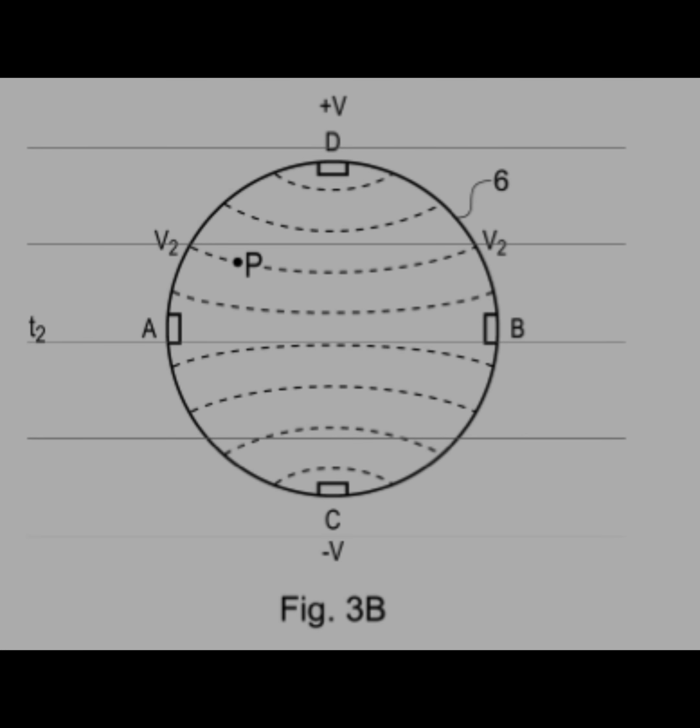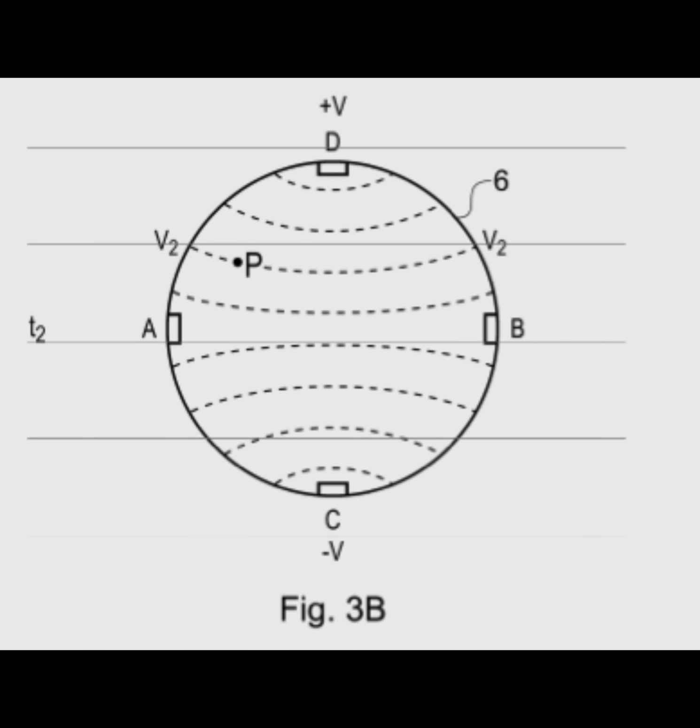Figure 5 shows a graphics tablet 21, which is a third embodiment of the invention. This graphics tablet comprises a panel and an actuator 24 which can be freely moved. The panel comprises a flat support 22 on which a resistive layer 26 is coated or glued. A first pair of contacts A and B and a second pair of contacts C and D are provided at the periphery of the resistive layer 26.